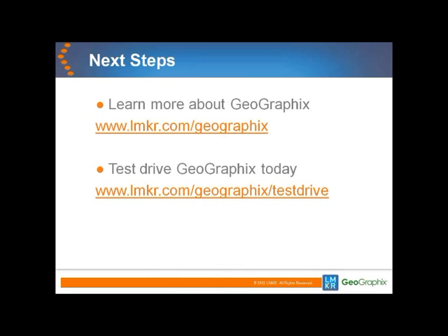There are a couple of restrictions. One is you have to be able to link the data in ARIES or in the economics package to a well ID in GeoGraphix in order to put it on a map. And the only other restriction is you have to have ODBC. It has to be an ODBC data source. But in this case, it certainly is, and it's fairly easy to do.